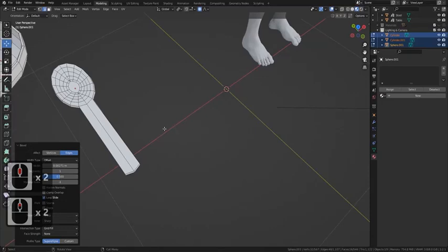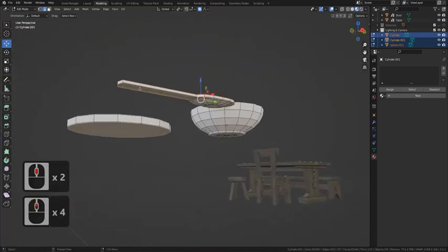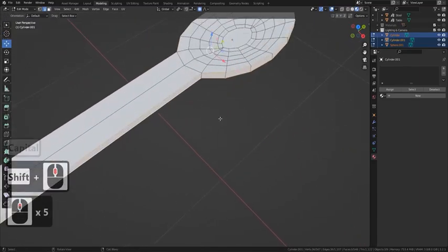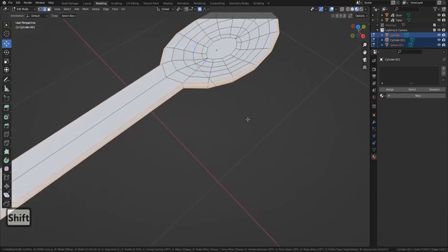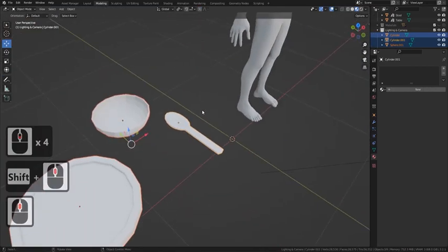And the spoon wants also probably a very, very slight bevel on it. So going all the way around the bottom and the top, like so. And this side, like so. Press the dot button, zoom in so I can actually use it. Press Control B, pull it in very, very slightly, like so, and that's looking a ton better.